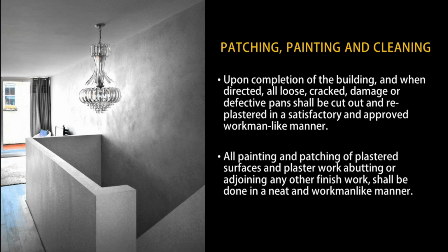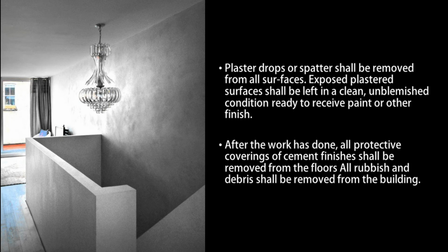Patching, painting, and cleaning. Upon completion of the building and when directed, all loose, cracked, damaged, and defective parts shall be cut out and replastered in a satisfactory and approved workmanlike manner. All painting and patching of the plastered surfaces and plaster work abutting or adjoining any other finish work shall be done in a neat and workmanlike manner. Plaster drops or spatter shall be removed from all surfaces. Exposed plastered surfaces shall be left in a clean, unblemished condition, ready to receive paint or other finish. And lastly, after the work is done, all protective coverings of the cement finishes shall be removed from the floors. All rubbish and debris shall be removed from the building.